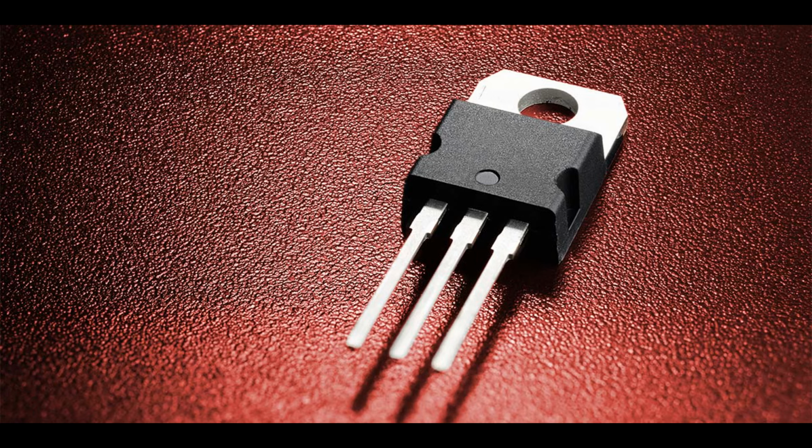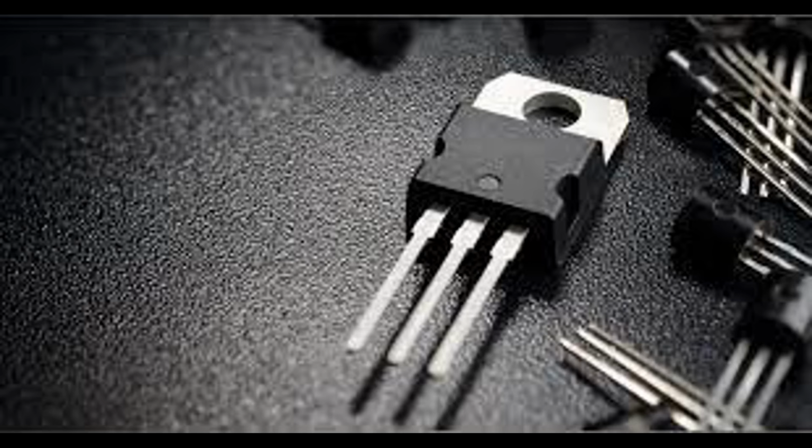4. DC-DC converters. Application: Commonly found in power management for portable devices, automotive electronics, and telecom equipment. Function: They convert one DC voltage level to another, providing regulated power to various components. 5. Lighting applications. Application: Used in LED drivers and electronic ballast for fluorescent lamps. Function: Power MOSFETs regulate the current supply to LEDs or lamps, ensuring efficient operation and dimming capabilities.